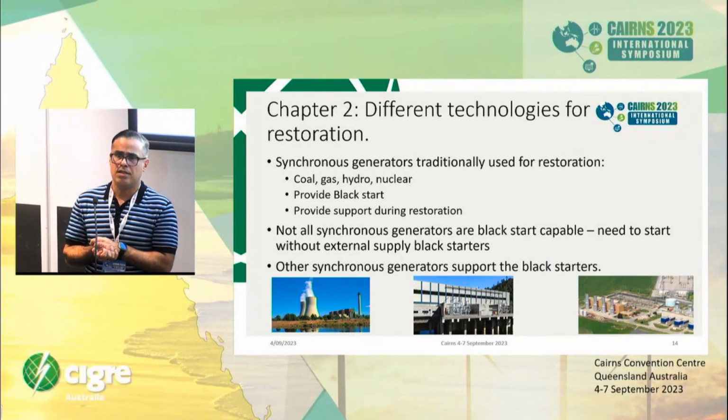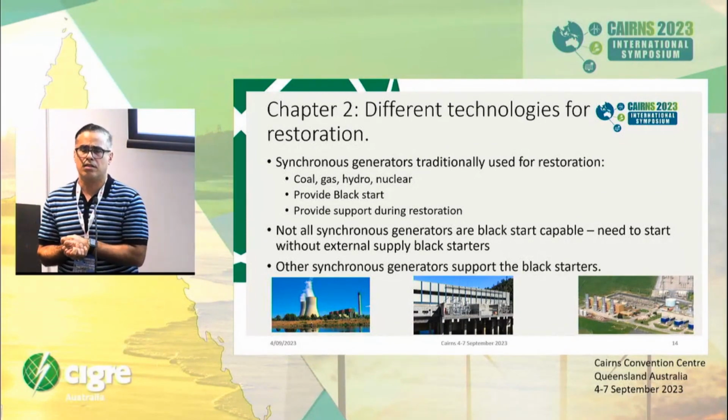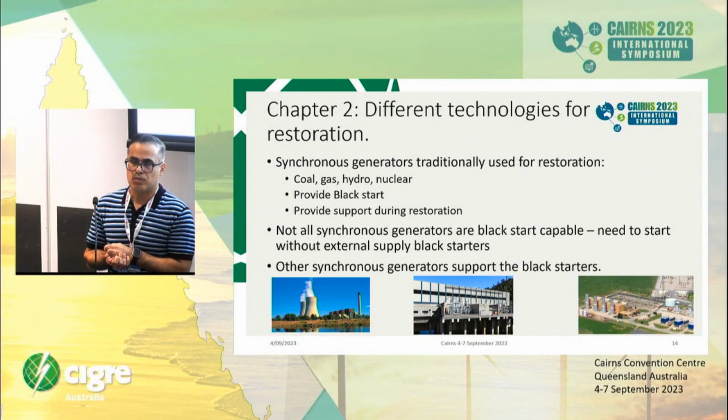As you go to much lower fault levels, there is a concern that protection may not operate. With inverter-based resources, you could provide the same level of faults, but that comes at a cost. The question is whether that is necessary, or perhaps to rethink what types of protection relays in the power system are most prone to maloperation during these very reduced fault levels. Prime examples are anything that acts based on current, whether overcurrent relays or fuses.